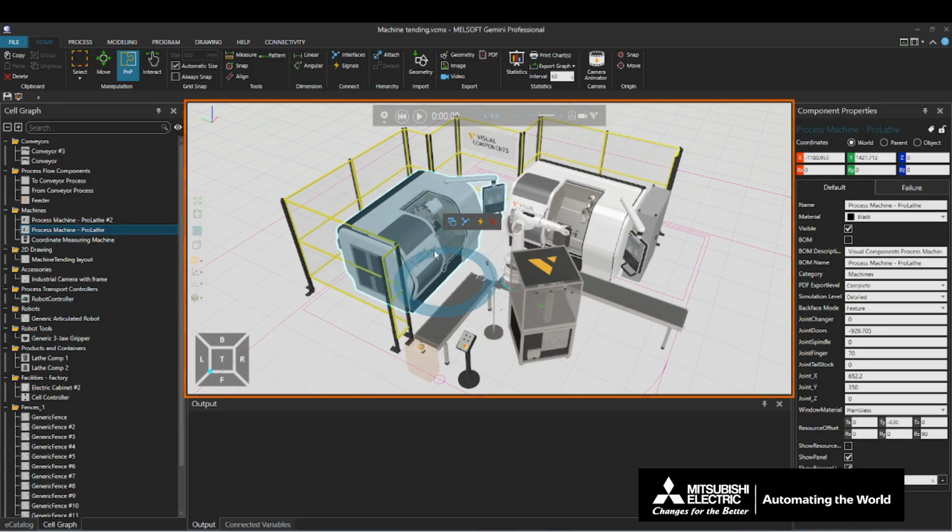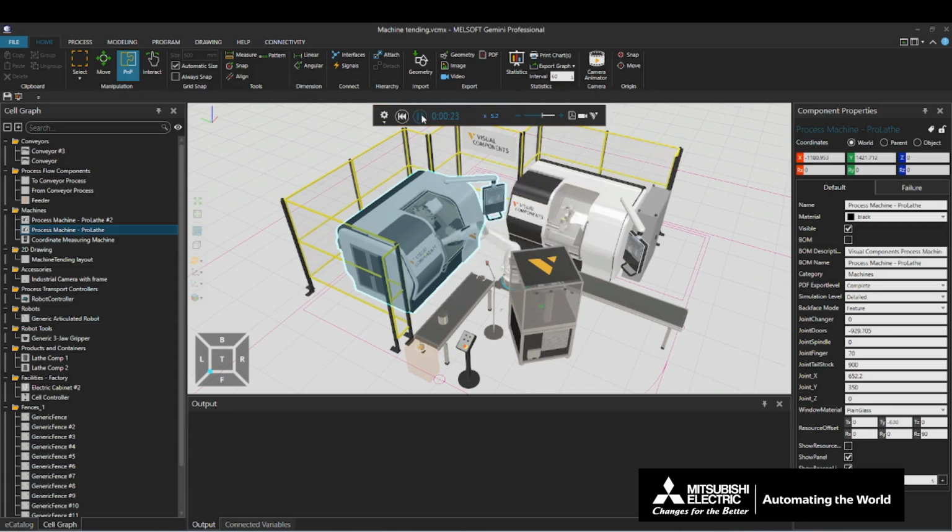The window at the center of the screen is the 3D World window. Here, you can place components and build a layout. On the top of the 3D World window is the Simulation control bar. You can start, stop, and reset the simulation, as well as change the playback speed. The object displayed on the top left of the 3D World window is the floating origin. The floating origin displays the direction of view the 3D world is being viewed from.